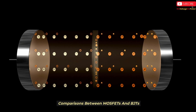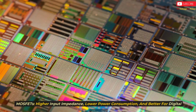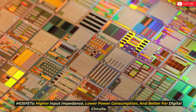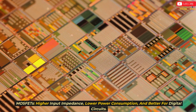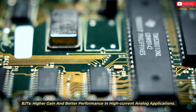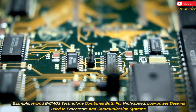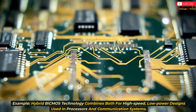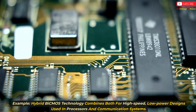Comparisons between MOSFETs and BJTs. MOSFETs: higher input impedance, lower power consumption, and better for digital circuits. BJTs: higher gain and better performance in high current analog applications. Example: hybrid BiCMOS technology combines both for high-speed, low-power designs used in processors and communication systems.